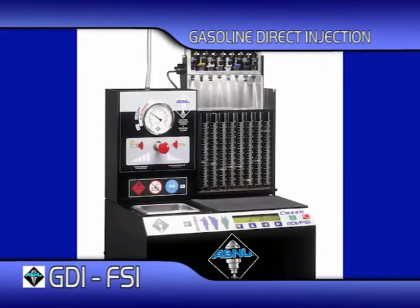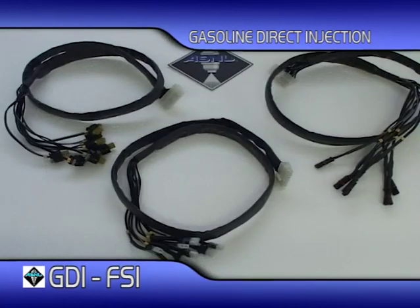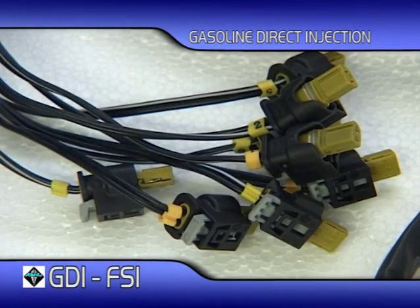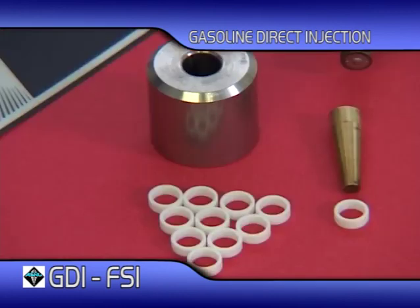The ASNU Classic GDI machine shown here and the ASNU GDI adapter box are designed to test and service any GDI injector currently in service. There are a selection of wiring harnesses and fuel rail connectors to adapt the system to any GDI injector. The system comes with a service kit to replace the Teflon head seals that require renewal before the injector is refitted to the engine.